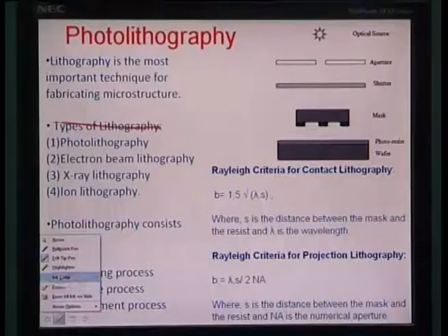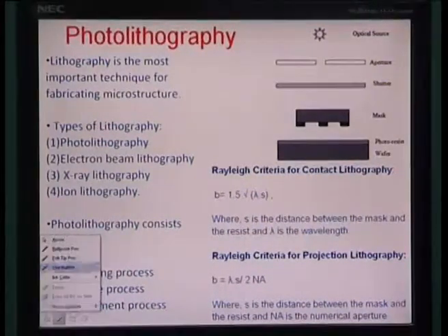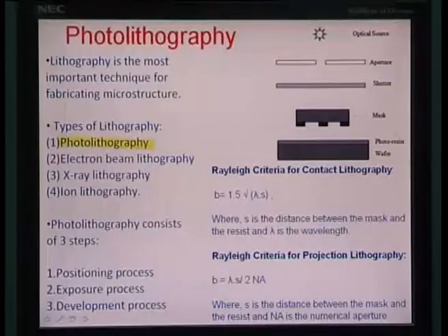So as you know, photolithography really is one of the most important techniques for fabrication of microstructures. If you look into just the lithography domain, you can divide this whole lithography business into several subtypes. You can have photon driven lithography, which is also known as photolithography. You can have electron beam driven lithography, electron beam lithography, X-ray lithography, ion lithography, so on and so forth.